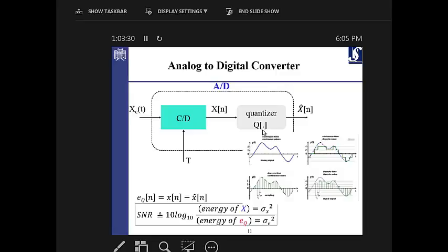But then it would be a different task if, for example, the input signal comes from 0 to, assuming the offset is more than 0, for example 15 or 50 volts. It means that the dynamic range is between 0 and 50, and you have to do something with this range. It depends on your application, whether you have prior knowledge that when people talk, the voltage is in the range of 15 or 10 volts, and not more than that, unless people start shouting or screaming. Then it goes beyond, for example, 30 volts as the input.